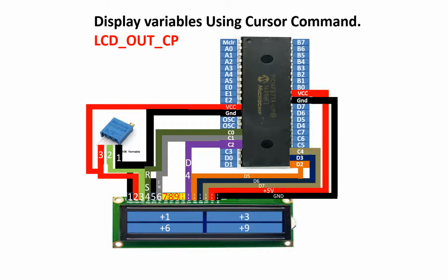Now guys, these 4 pins, pin number 7, 8, 9 and 10, are for the 8-bit mode, while we are going to use this LCD in the 4-bit mode.